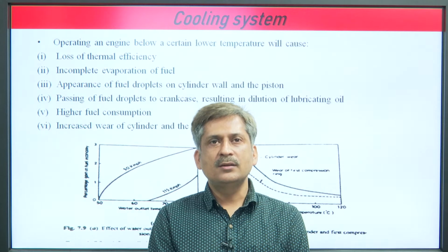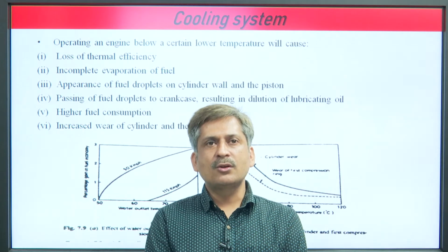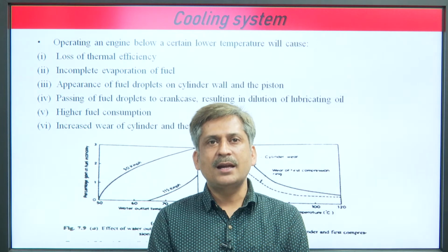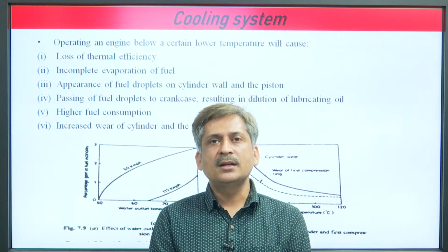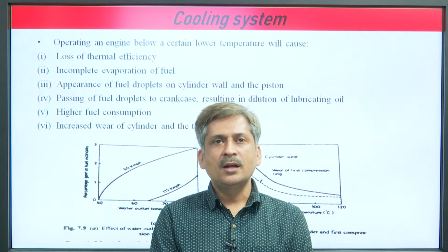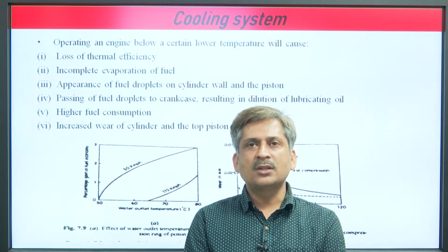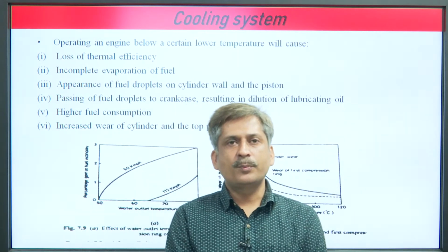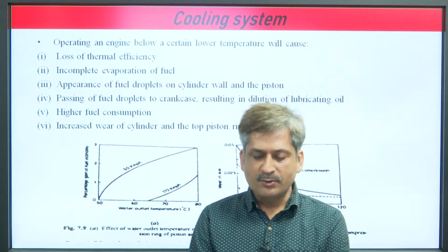We have also discussed that incomplete evaporation of fuel leads to higher fuel consumption. It disturbs the mileage and performance of the engine, and also affects the emissions. Because of the effect on the lubricating oil film, if effective cooling is not there, increased wear of the cylinder and top piston rings will occur.